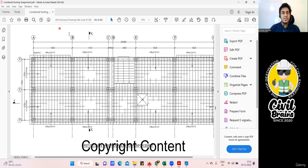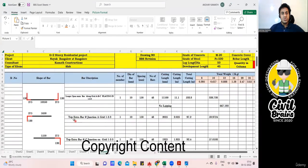So first I'll find the cutting length for this particular area. I want to find the top left bar first. In this way, in this junction, A to B, 1 to 2 and 2 to 3. This much I'll find first. So how do I write? Very simple. I'll write at junction A, because I'm conducting at junction A, and it is going along the grid 1, 2 and 3. Okay, remember that. So same thing I'll write: top extra bar at junction A and in the grid 1, 2 and 3. Simple. And the shape will be like this.